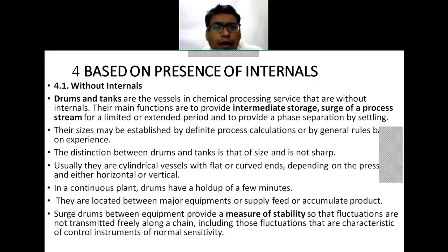It is not that if it is above 2 meters, you are calling it a tank, or below that a drum. It is not like that. It depends on its function. The main function is to provide the intermediate storage surge, whether for limited time or extended period. Then usually they are cylindrical vessels with flat or curved ends. Generally the flat end, which we see in our day-to-day life, the drums are of a flat end. But in case of the industries, they can be curved end also, depending on the process requirement.